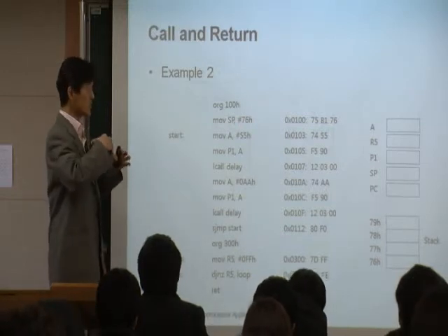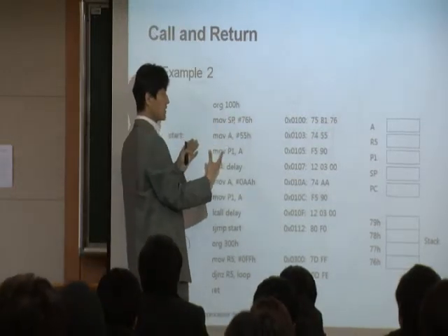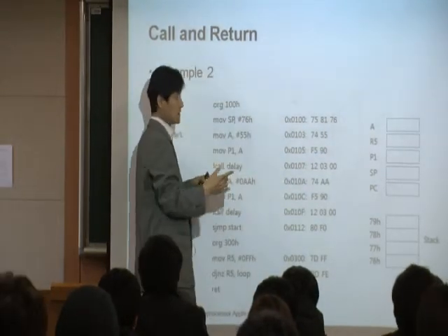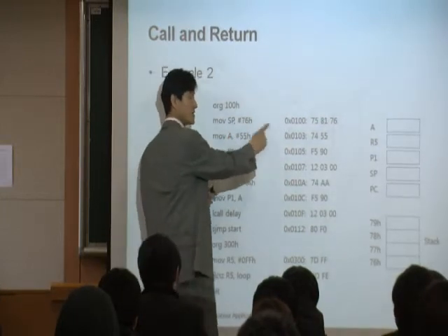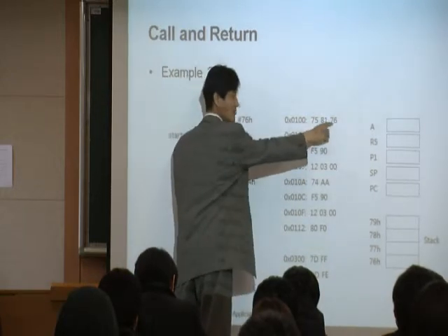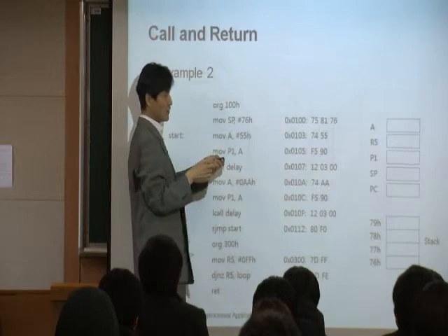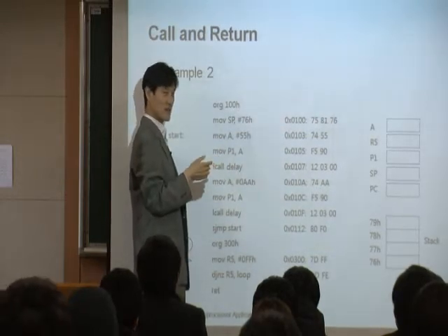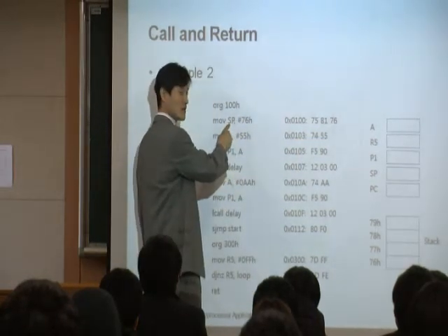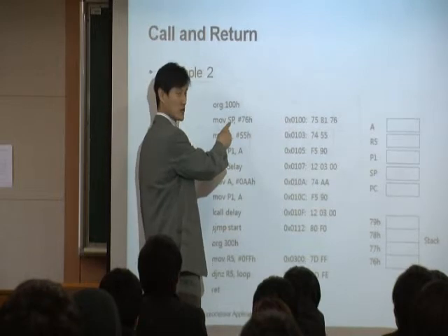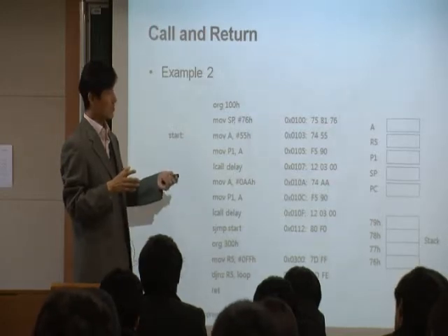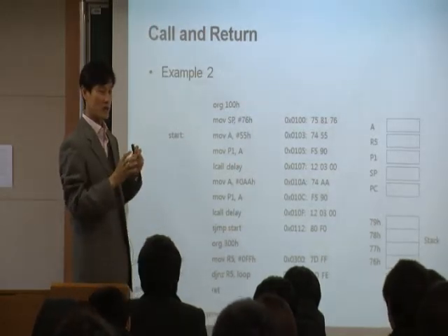When you run the assembler, it will convert this instruction into binary like this. See that the operand is still there, and this one actually is there. And why do we have these three? I mean, this one looks like a simple instruction, and we have three of them. Why is that? This value is still here. Stack pointer, what is the address of the stack pointer? Stack pointer has its own address, which is 81. 81 is the address of the stack pointer.